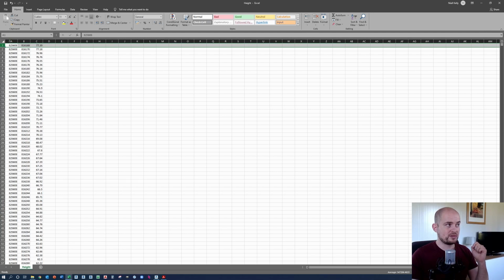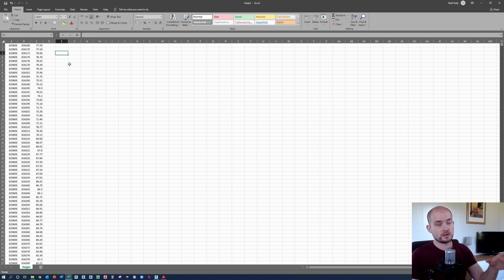And quite simply, what we're left with is our eastings, northings, and our relative elevation above sea level. And this is the format that we need for Civil 3D or Revit or any other CAD utility to read the information off of. Finally, the last thing you need to do is to ensure that you save the file as a .csv or comma separated value file. And that's for the software, for Civil 3D, CAD, Revit, and so on, to be able to understand the separators between the values for each point, okay?